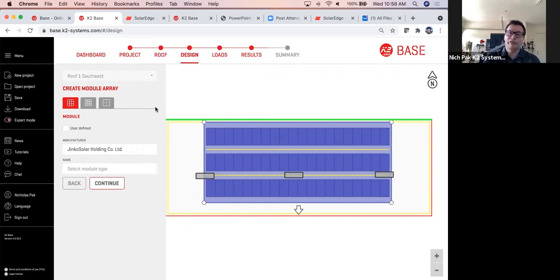In many cases, you might have to get a structural engineering letter from that particular area and from that building, or an architect that worked on that building or has had the chance to operate on that building, so they can actually see if the roof could handle upsloping the array on that particular metal roofing. But it has been done. It's definitely not a no. It's not a game over. It just has to be confirmed that the roofing material can actually handle that kind of loading and that kind of uplift.